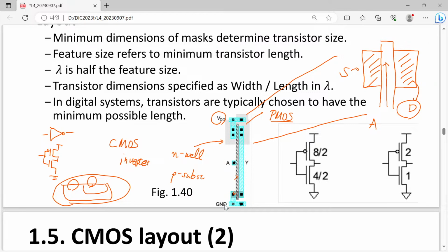Where can you find the MOSFET? Can you point it out? So you can find that this is your MOSFET. Still, you have a signal, the gate, and the gate is driven by your A signal, and one diffusion is connected to the ground, and another one is connected to Y. So that is once again another transistor called NMOSFET.